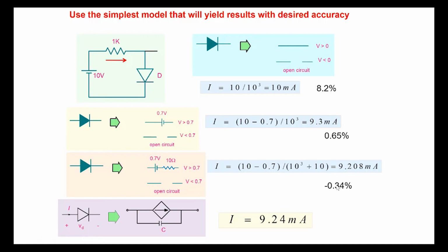Keeping in mind that, whenever we are taking a practical circuit and modeling it as a schematic like this, there are many approximations being made in that. Remember that even the resistor 1K may not be exactly 1K. It may be 0.9K because of tolerances. Similarly, the diode IS and saturation current may not be what we think it is, because there's a tolerance associated with everything.